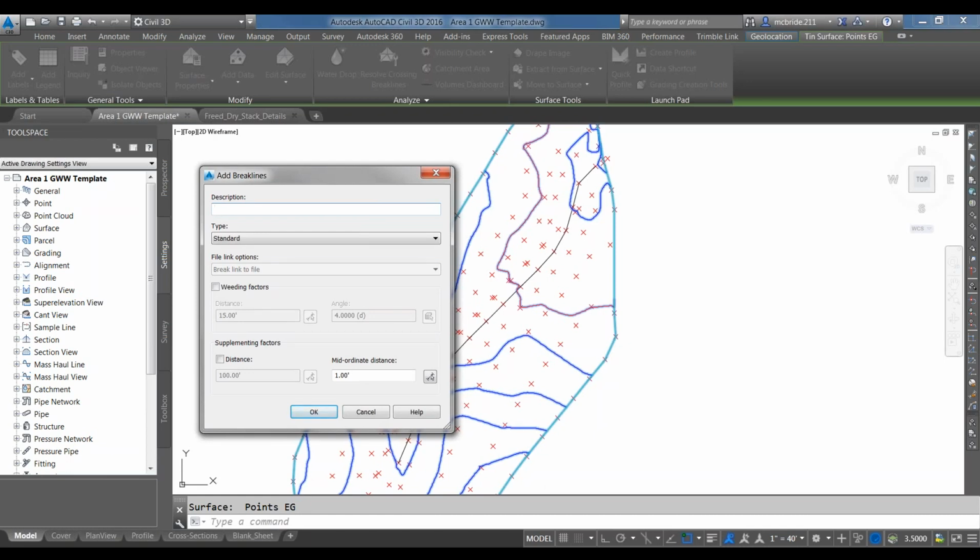That's the reason why, if you use the polyline like I did, you want to make sure you snap to all the points. However, like you said, if you use a feature line, you may not have to because you're already giving it the elevation at the point. I'm not too familiar, but I'm guessing that's the difference. So if you're using feature line and it's still working, keep rolling with it. It's not a problem.